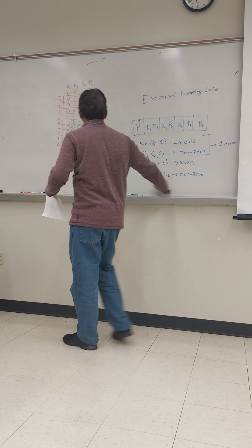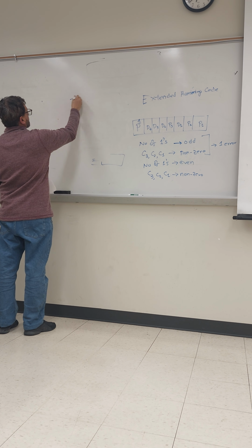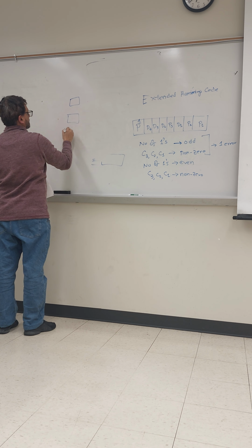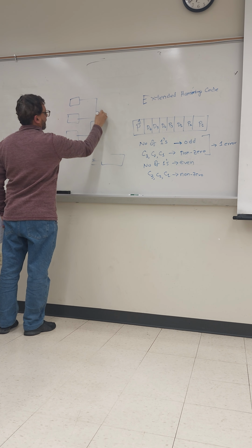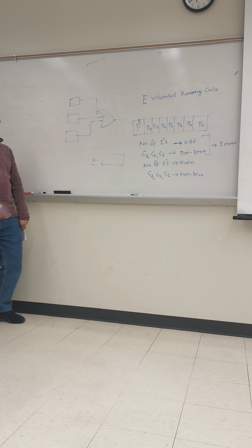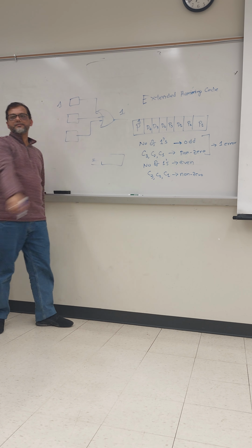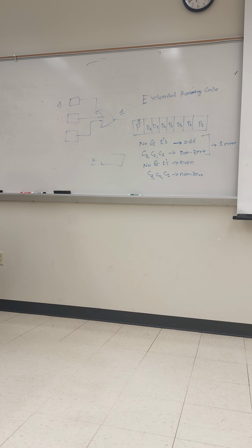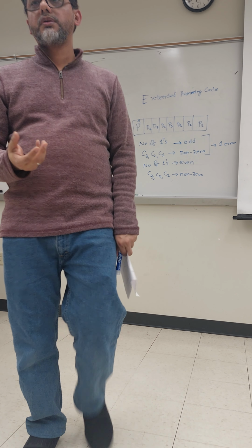So for example, if I can draw, so this is one window, two window, and one door. Then we give the connection to the OR gate. If any is open, any input is high, output will be high. This is how. So this is just a simple example. So you need to prepare yourself for the example. Maybe I will give you the scenario. You have to design the circuit. How you can design the circuit.